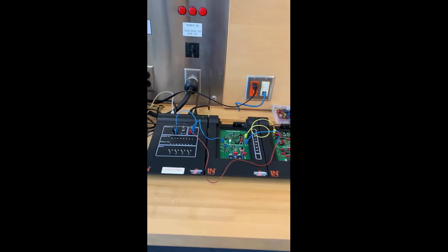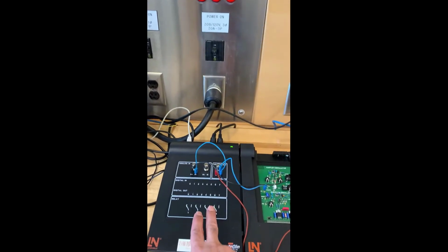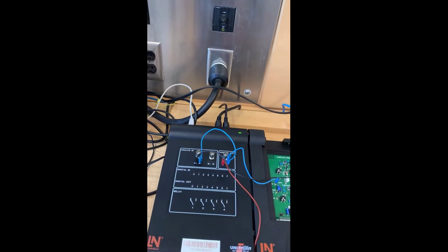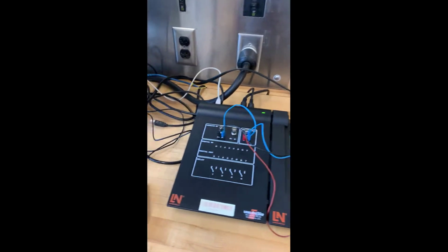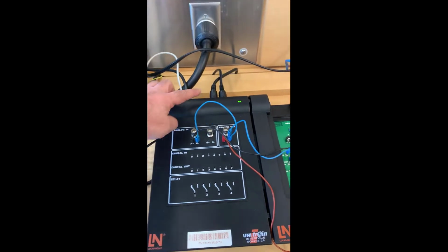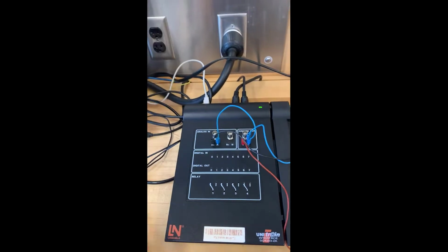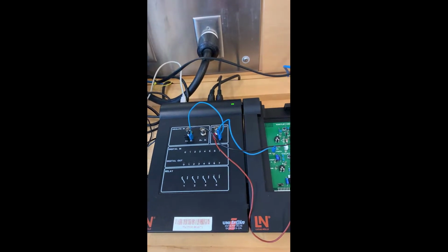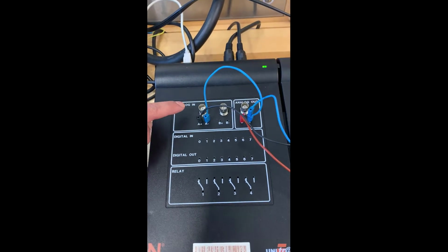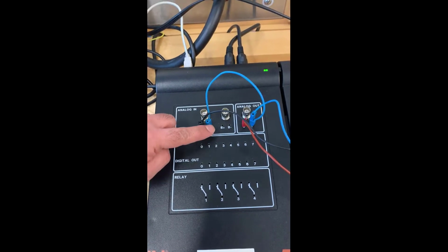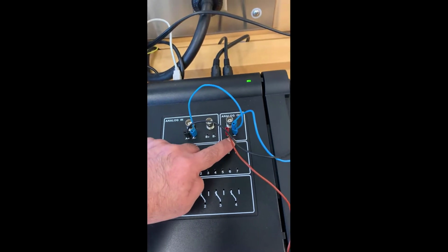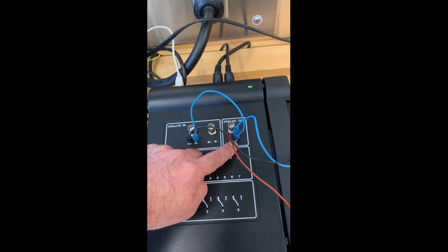It includes a module that we call the interface, which is the one that gets connected to the computer using a USB connection. And then these are for the power supply that they go to the transformer to provide the power for the unit. The interface has two channels, channel A and channel B. These are our oscilloscope channels for monitoring, and this is output for the function generator.